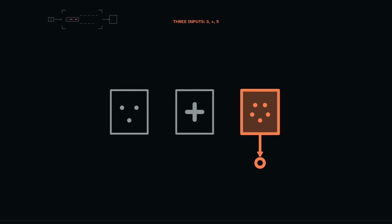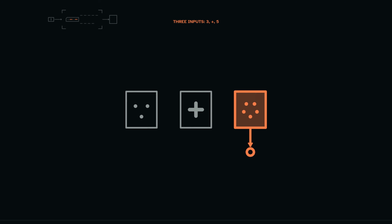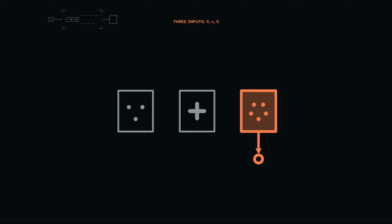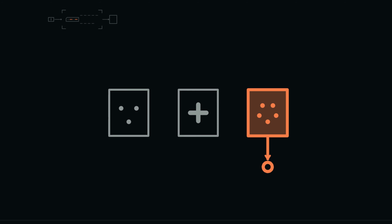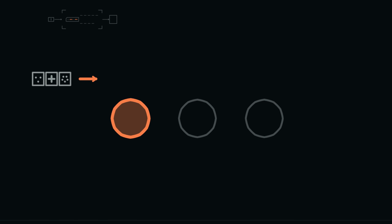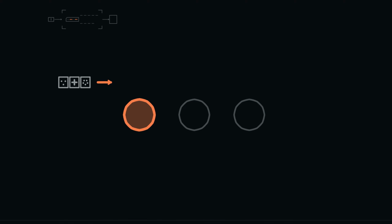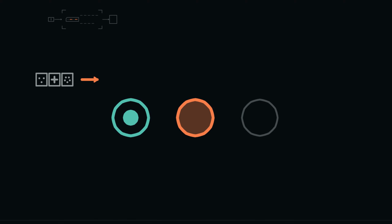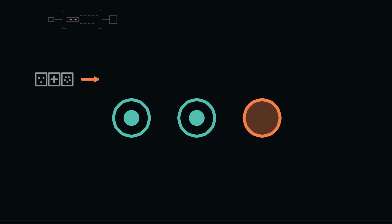The signal we inspect for the first key press belongs to that first event alone. It is not a joint signal for 3, plus, and 5. These reports preserve order, but none yet asserts a text character until the layout and modifier rules are applied. The input adapter applies those rules separately to the 3 reports. In this setup, it produces 3 ordered text bytes: hexadecimal 33 for the character 3, hexadecimal 2B for plus, and hexadecimal 35 for 5.